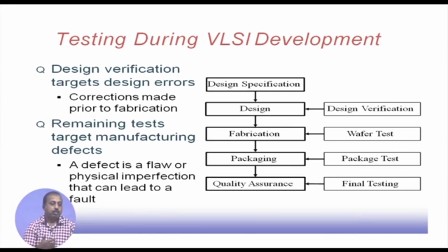It may be that we do it in some hardware description language, VHDL, Verilog, etc., or we write it in some other specification technique, from which a conversion is done to the behavioral description or structural description of it. Then after this specification is given, it passes through some design process, basically some CAD tools, from where we get the design.